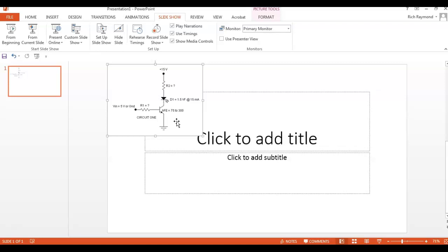So what we could do, and I don't know if I've got that data sheet up there, I need to bring it up, but we've got a generic data sheet that shows you the colors, shows you what they're doped with, and it gives you the basic VF of the diode. I'll make sure it's up there because that way you don't even need the data sheet. You can just look at the color. By the way, the lens enhances the color. The color of the LED is determined by how it's doped. This is why you can see a clear lens LED and it might be glowing red. It's just not going to appear as bright as one with a red lens on it. Does that make sense?